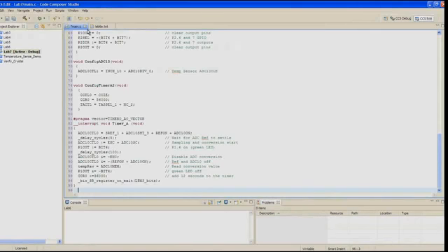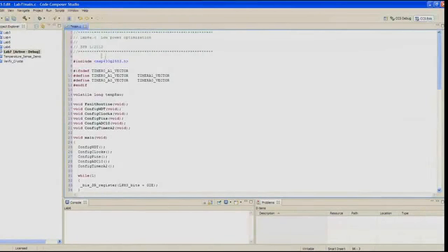You should notice this is not the low power optimized code that we created in the last part of the lab 6 exercise. The software UART implementation requires timer A2, so using the fully optimized code from lab 6 wouldn't be possible. But we can make a few adjustments and still maintain fairly low power. Go ahead and close the lab6a.txt file, and if you're using the 2231, make sure you make the appropriate change to the header file at the top of main.c. As a test, build, load, and run the code.